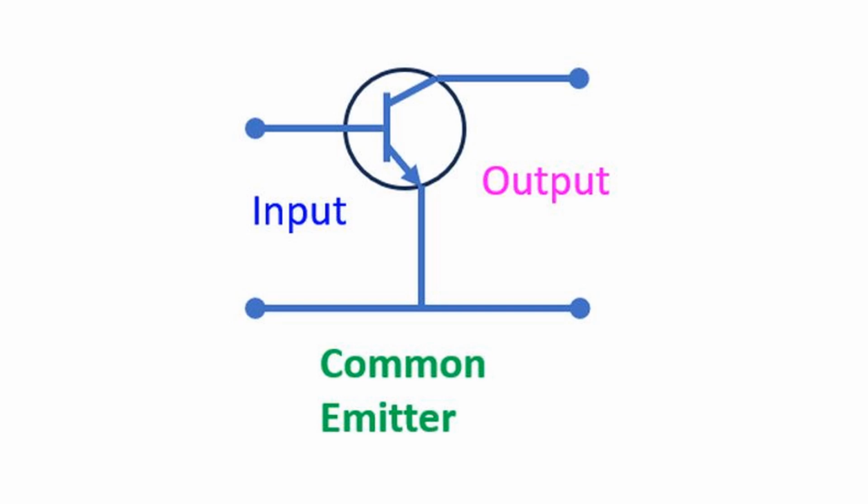Most common type is common emitter configuration, in which emitter is grounded, base acts as the input and collector as the output. So the input is given between the base and the emitter, which is grounded. Current gain in this configuration, which is the ratio of collector current to the base current, is known as beta or HFE, which stands for hybrid parameter forward current gain common emitter.